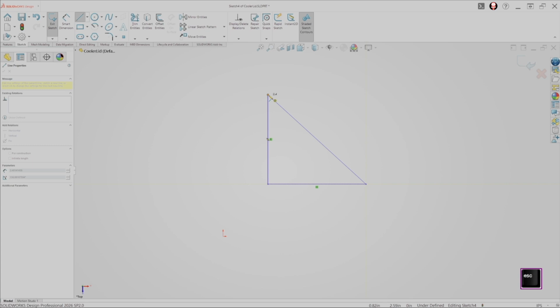In this case, let's go to the top and use the same methodology. So I'm going to go up to the top. Let's hover over to the right until it snaps vertically and then click with our mouse. I'm still working in a continuous line, but right now I'm just going to close off this box, which should create a horizontal line and then complete the shape, turning it into what's called a closed profile. So we can see that the square is now filled in. When that shape fills in, just as a reminder, it's called a closed profile or an enclosed region that can be extruded or revolved to create a 3D body.